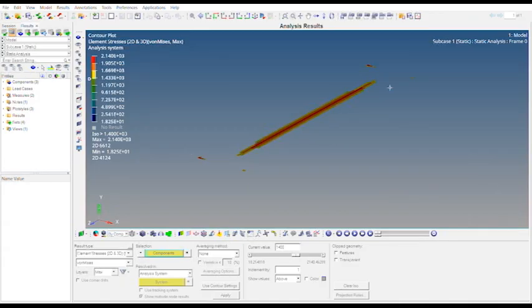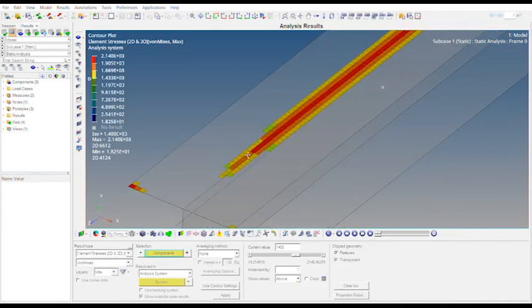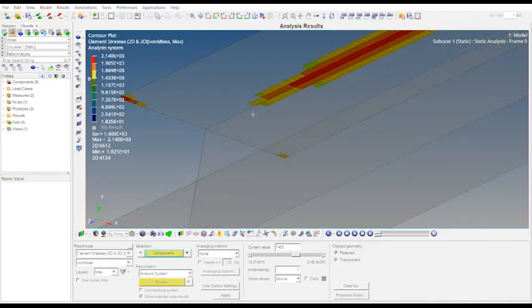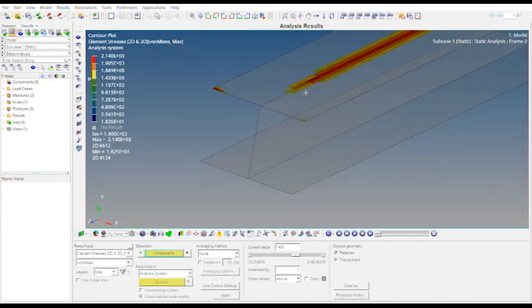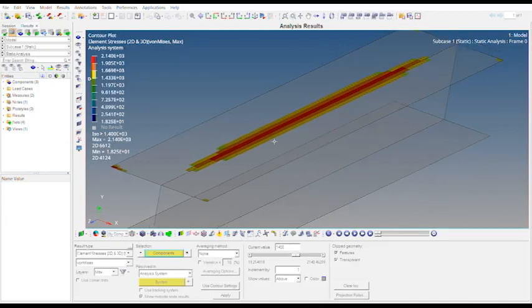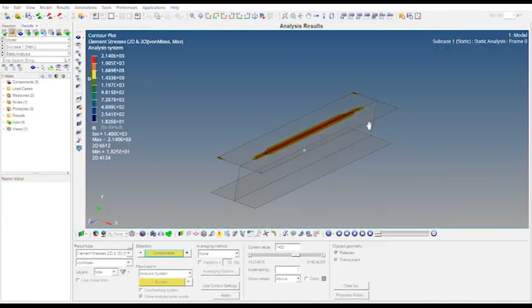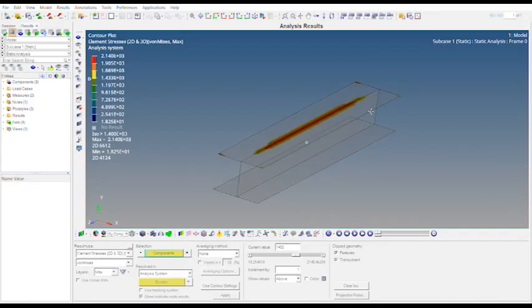So how do we overlap it on the geometry, the component? We can just go here, features, transparent. You can see the regions where those stresses are higher on the geometry. You can see it's about the center line, and it's diverging here a little bit, spreading out, and in this corner part, all these elements have stresses more than 1400.